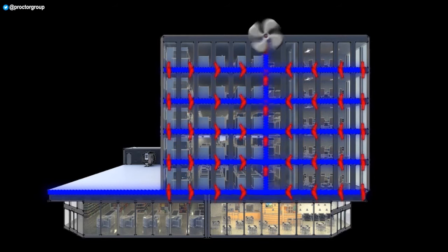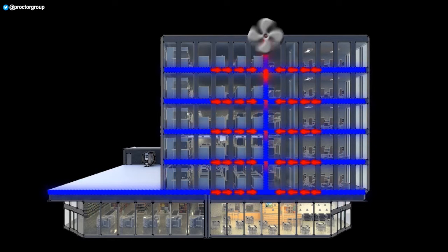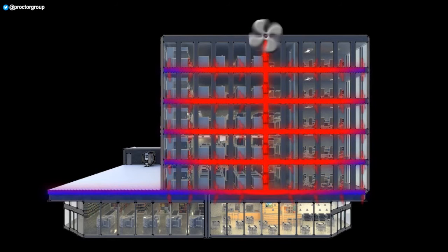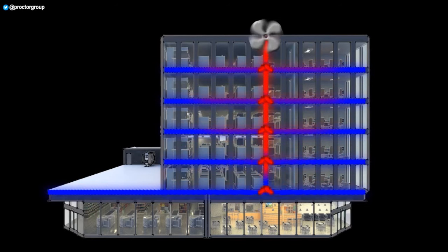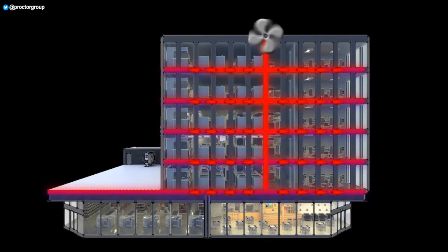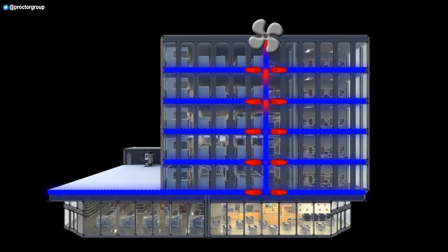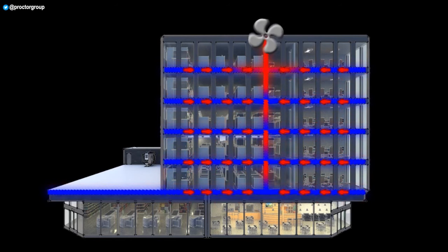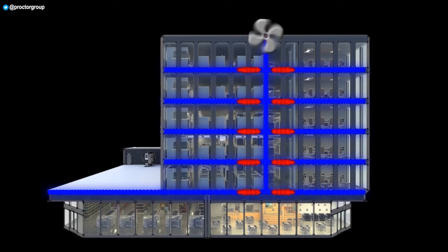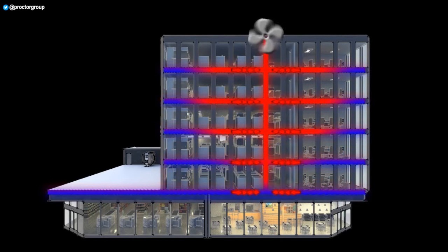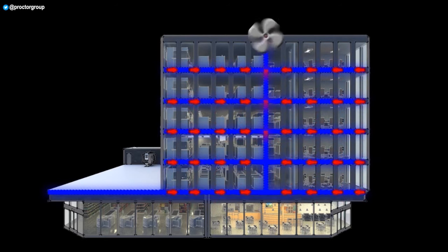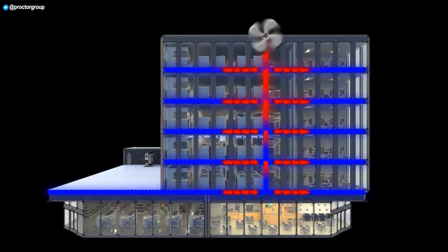Natural sources produce pressures of up to 10 pascals, while mechanical systems can go as high as 60 pascals. If this is not managed correctly, it can contribute by drawing air into the building envelope from unintended sources. Additionally, if the system is not installed well, leaking ductwork may draw air into the system that has not been accounted for, with a corresponding detrimental effect on the efficiency of both the system and the building as a whole.